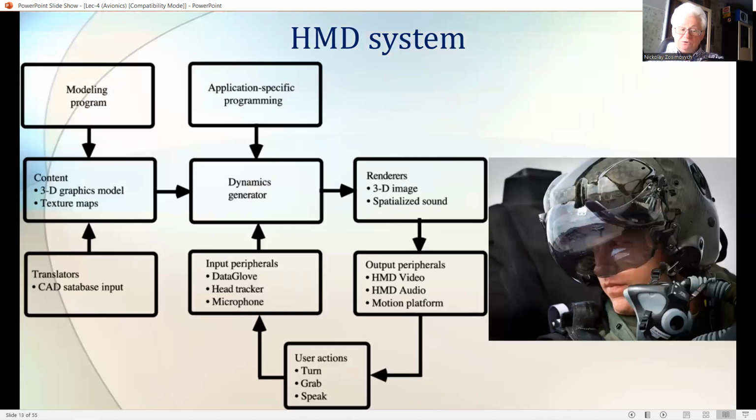The integrity issue, however, is not an insuperable one, with the advances being made in display technology and the incorporation of adequate redundancy and monitoring into the system. Clearly, the integrity of the display of primary flight data, such as attitude information and heading on the HMD, is dependent on the correct function of the head tracker system.